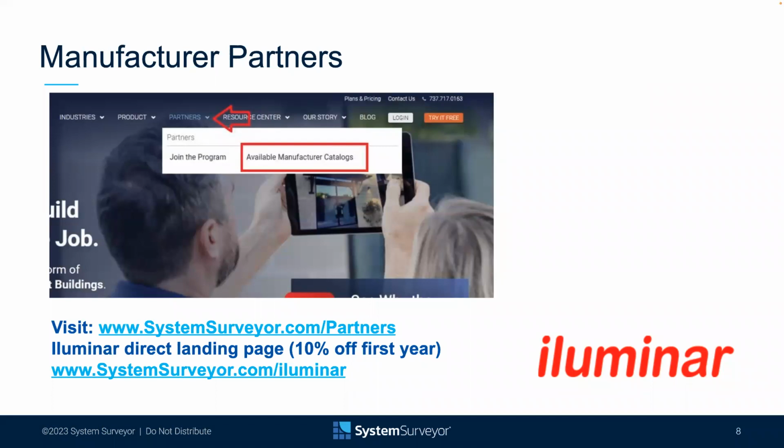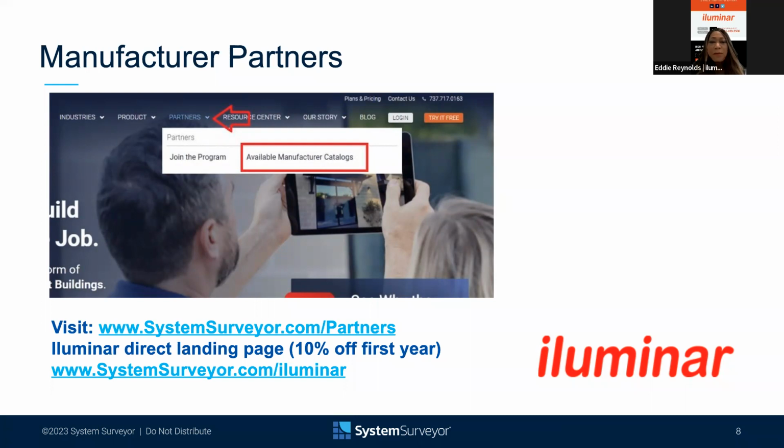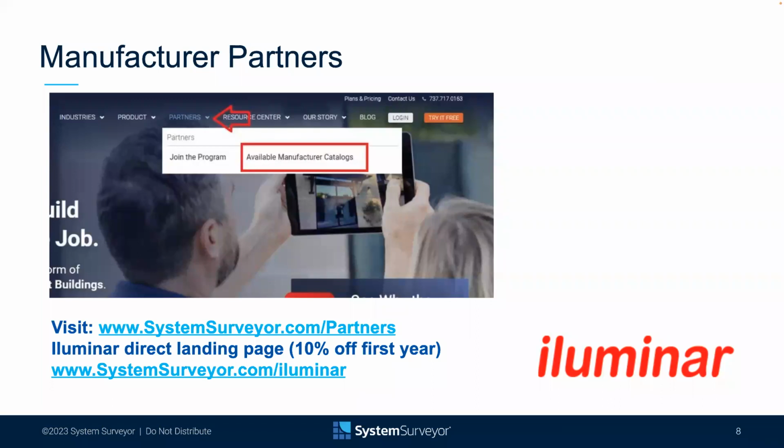Wonderful. Okay, great. And are the Invisible series and the Opto series both the 850 nanometer frequency? Yes, so with our products, the standard is 850 nanometers. In the part number, for instance the IR148, if it says a -A on the product, that's an 850 nanometer, which is standard, which is pretty much what you want to use for better performance with your infrared illuminators. The C is a covert, that's 940 nanometers, where you don't see any red glow. And then we also have white light, which are all WL prefixes. White light is a visible light that allows your camera to see in color 24 hours a day. Wonderful. Great. Thank you so much.